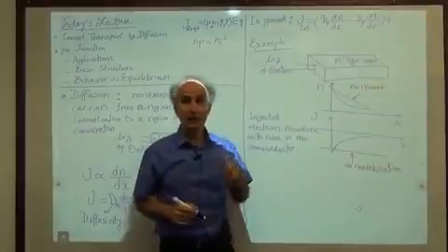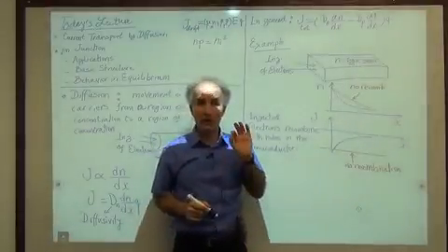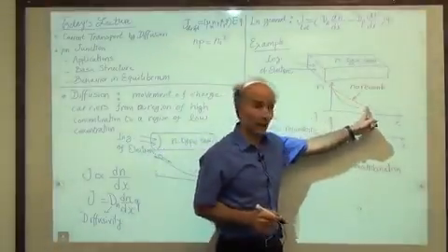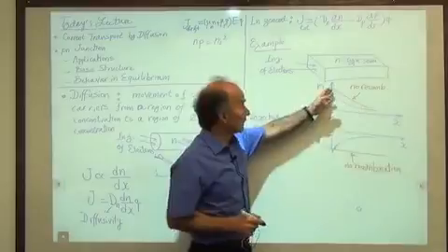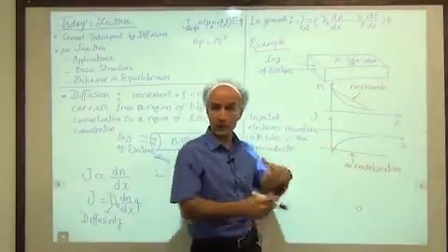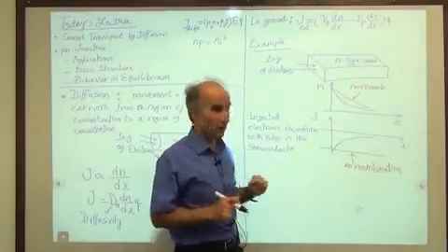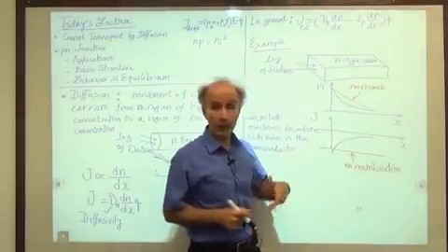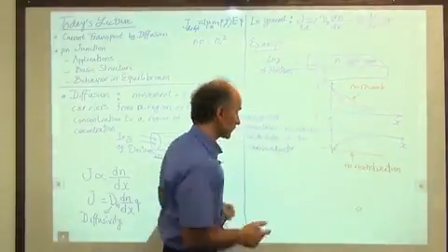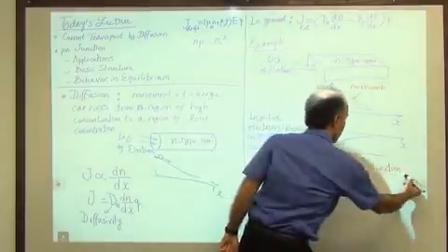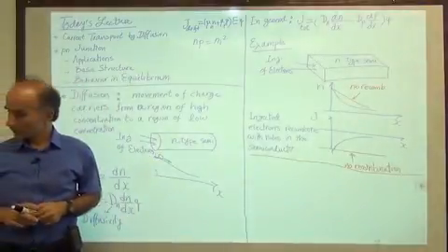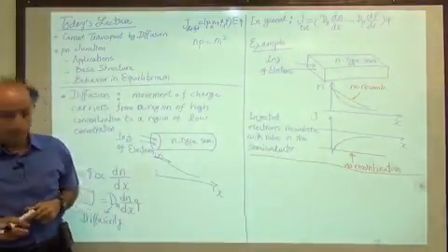So you see that diffusion still occurs. The gradient in concentration still exists, but it's a straight line. So if that's the case, then the current is constant. The current is carried primarily by the electrons. There are not that many holes in there, and everyone is happy. On the other hand, if the holes are not that small, then we will see something like this, and we'll see something like that. All right, very good. Let's move on, and let me just mention a few more concepts here.